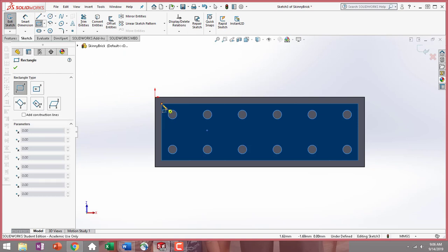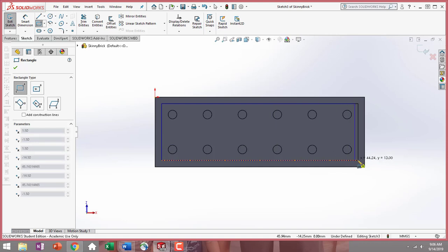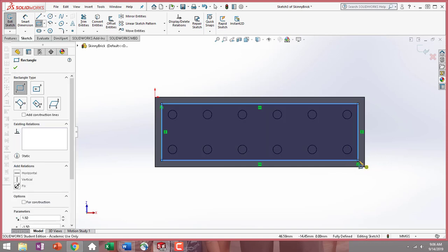Now you need to make sure your rectangle is connected to the endpoints inside that sketch. If it is not connected, you will have problems later on when we change our global variables, because your part will grow, but your underneath cut will only stay the size that you set now.